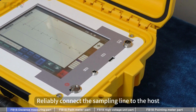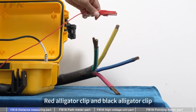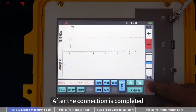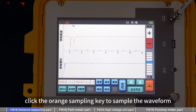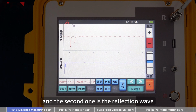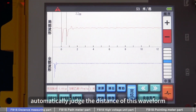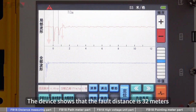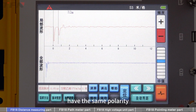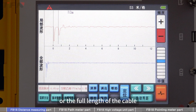Equipment connection. Reliably connect the sampling line to the host. The red alligator clip and the black alligator clip respectively connect the 2 measured cores of the cable. After the connection is completed, click the orange sampling key to sample the waveform. The first one is a transmission wave, and the second one is a reflection wave. Click automatic distance judgment to automatically judge the distance of this waveform. The device shows that the fault distance is 32 meters. The transmission wave and the reflection wave have the same polarity, indicating that this waveform is a disconnection waveform or the full length of the cable.